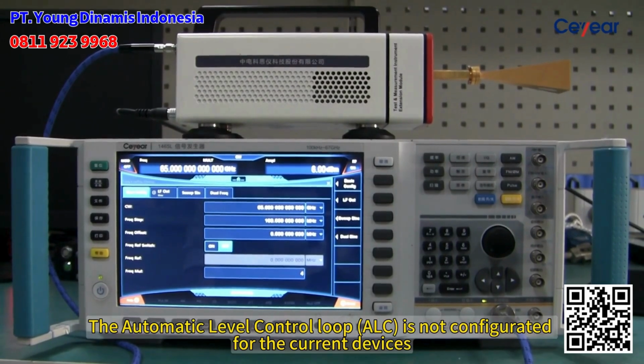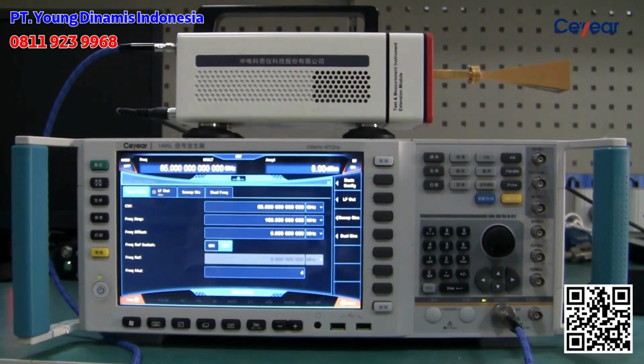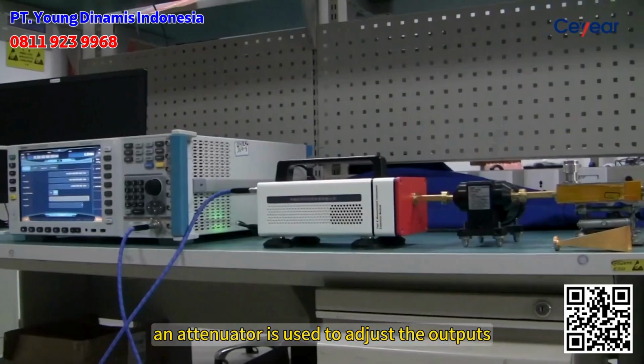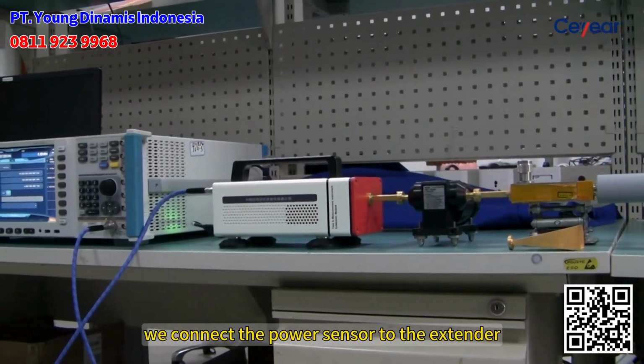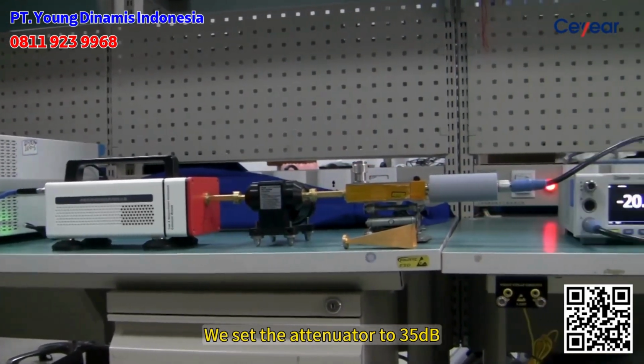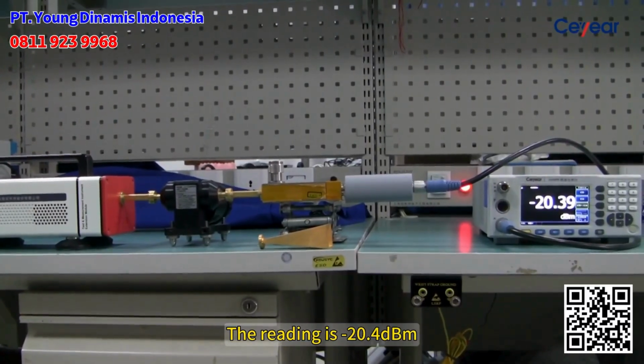The automatic level control loop is not configured for the current devices. So an attenuator is used to adjust the outputs. After calibration, we connect the power sensor to the extender. We set the attenuator to 35 dB. The reading is minus 20.4 dBm.